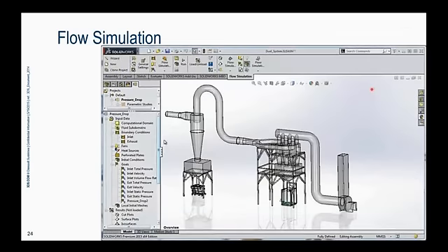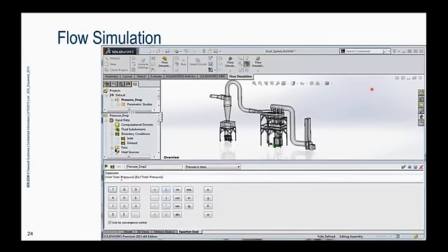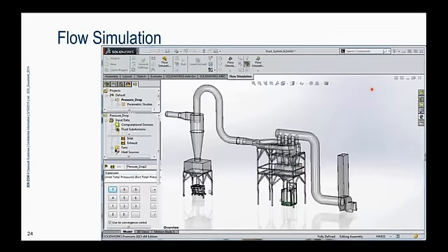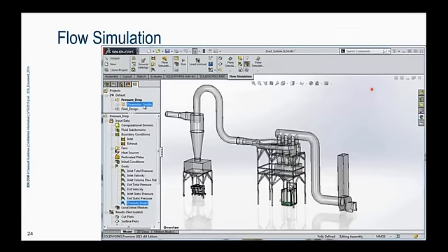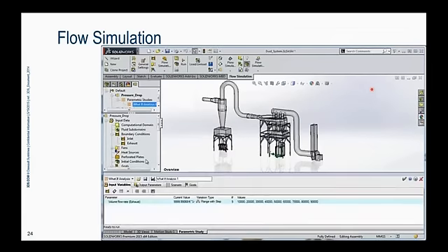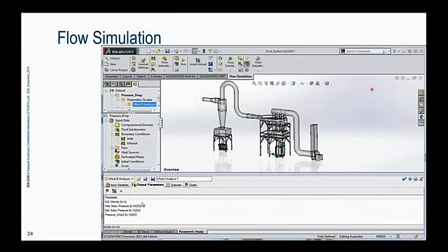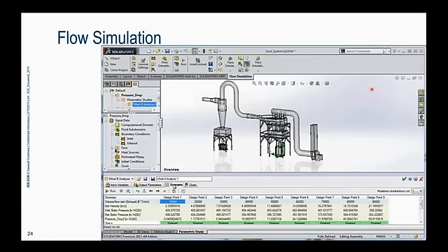So in SolidWorks, it's pretty simple. We just specify an atmospheric pressure on our inlet, and specify a volume flow rate on the outlet to the fan. Then while we're doing that, we want to measure the pressure drop as a simple equation. And then we create a parametric study, which is like a design study, where we can vary that volume flow rate. We can vary other things, but that's the goal for this case. And then monitor the pressure drop and exit velocity, and do that over a range of volume flow rates. And then we have all of the results to generate our curve.